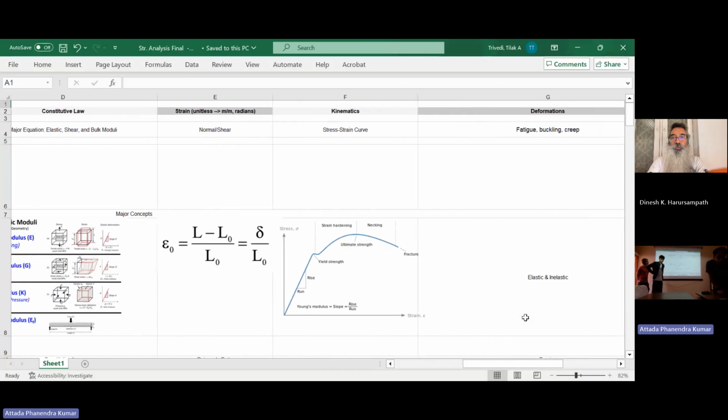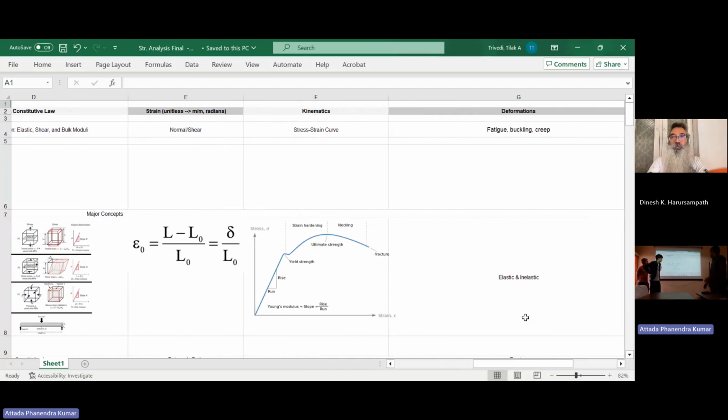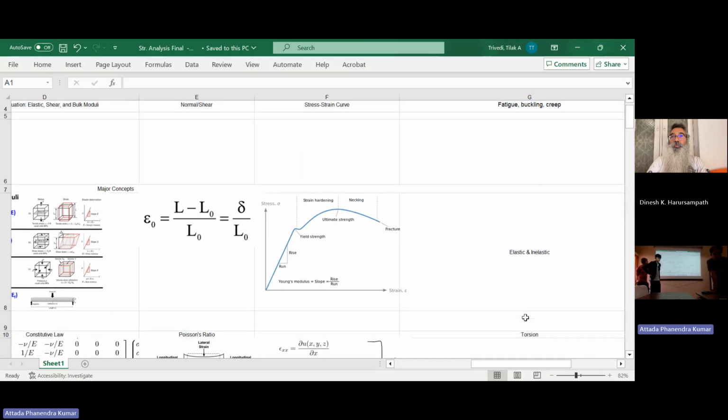The whole point of that was to talk about how it leads to deformation, where we always say in the elastic region, we can reverse whatever change in loading condition, or reverse the conditions that we applied, and still return to a reasonably usable structure. Whereas once you reach beyond the elastic region, we have plastic deformation, and it can also lead to points of weakness in the structure.